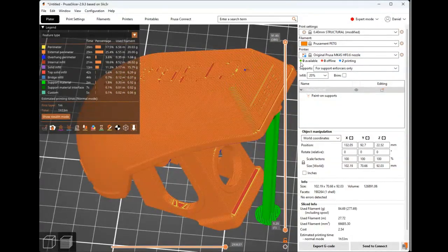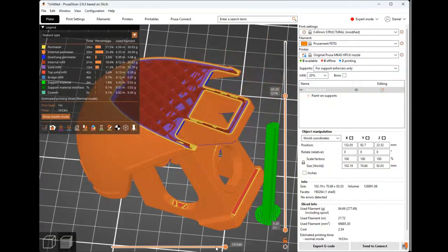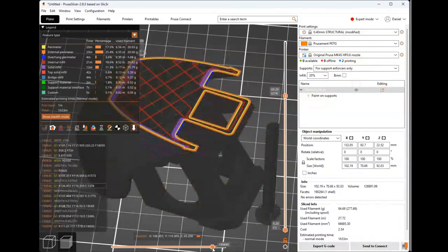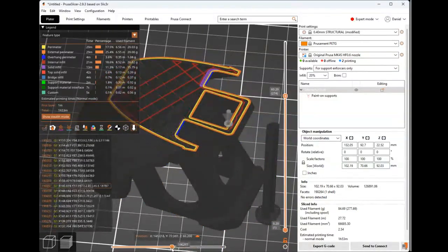Over on this side, let's say you're in the middle of something, you can scroll this second scroll bar to see the exact movements of the machine as it makes the part, and the actual code that gets sent to the machine. G code is actually incredibly easy to read. G code stands for geometry code, and it's just a series of coordinates with a command.